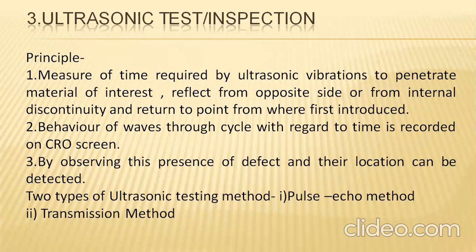So what we have learned till now is that in the case of the liquid penetrant testing process, the liquid or penetrant is applied on the surface, and only surface-level cracks up to a particular thickness, up to 2 mm or 3 mm, can be identified. Basically, only those cracks can be identified in the liquid penetrant testing process.